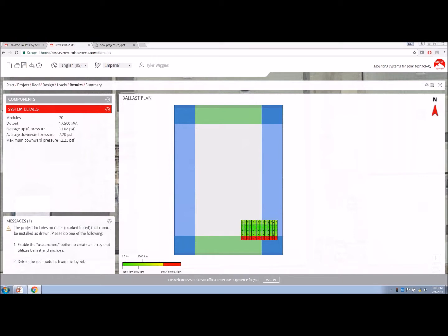Okay. Any more questions? Okay, I have another question here. When you say paver, I am to assume that they are solid blocks, right? Yes, for that paver, it is a solid block that is 4x8 by 16. I have seen those come in as 4x8 by 16 blocks, but they're 16 pounds. And I've also seen them come in at 32 pounds, that's the standard one that we recommend for installations. So 32-pound block, that's 4x8 by 16.